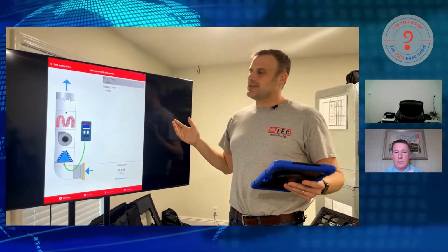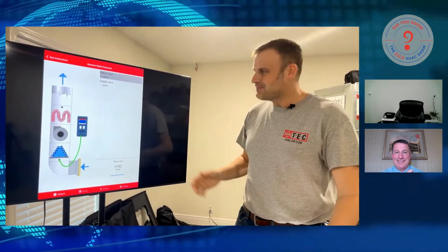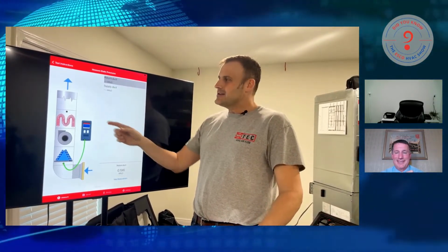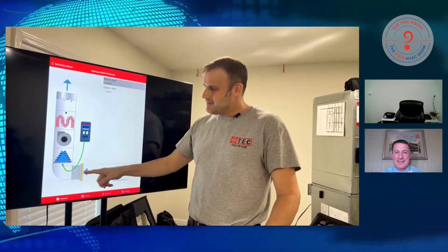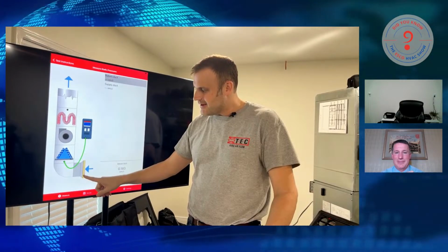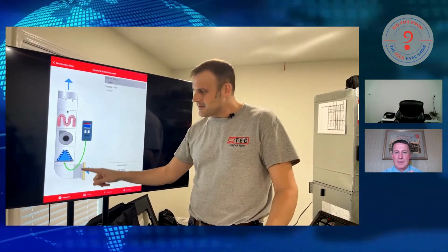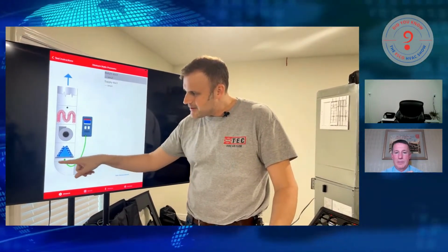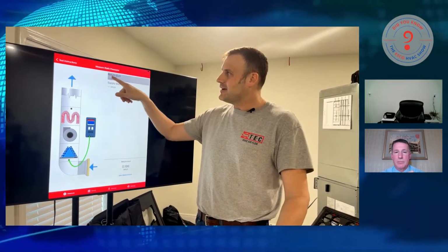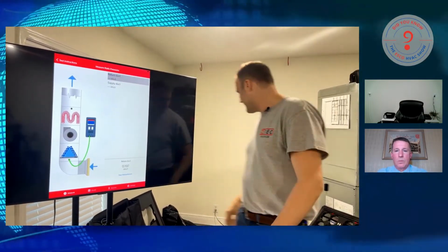Now we're off to the races. Here's what I love about this app. Every time you make those workflow selections, we will paint you a picture of the install that you just entered, right? Yeah. So you'll notice our filter is in the grill. If you select filter slot, we're going to rotate that picture and put it right here. And we have those dots, right? That's showing you where to put your static pressure probe when you're taking these measurements. In that application, we're saying return duct, right?